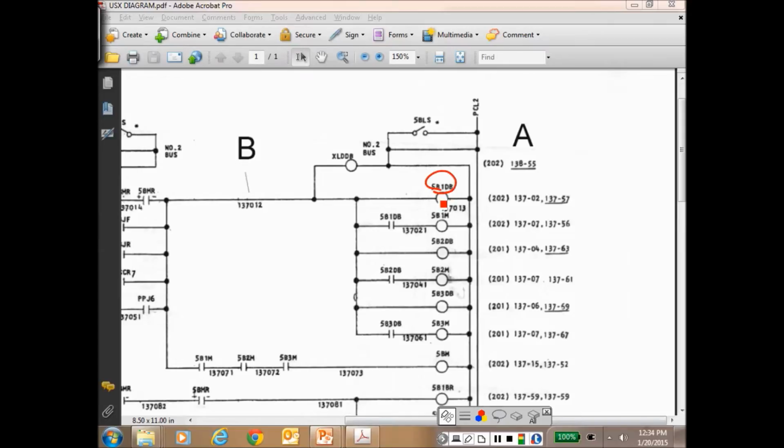Now most of ours will put a little letter inside the symbol, but odds are when you get out on a true line diagram, they're not going to have enough. They've got so many relays they can't just call them M1, M2, and M3. They've got to give them bigger names, right? Understand? And then it tells me what line they're in, and whether I'm looking for a normally open or normally closed contact. Then every contact has a name above it, and we're looking for a name that matches the relay name that we're trying to find. That make sense?